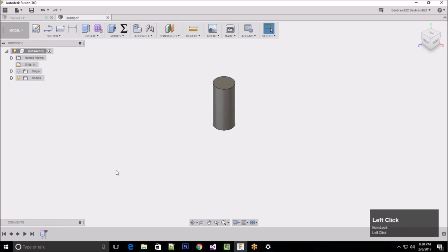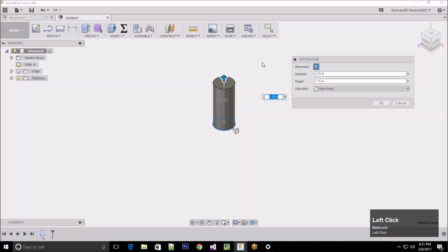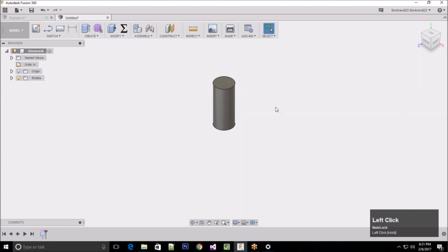You could be a little bit more limited there because you can't go in later and say, oh, I don't think I really wanted a cylinder, I wanted to extrude a little bit of a different shape. So you can't really edit that sketch. So there, that could be a limitation. So I typically don't use those primitives just because I like the flow of making a sketch first and then extruding it out.